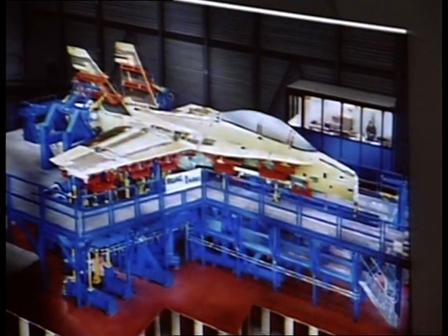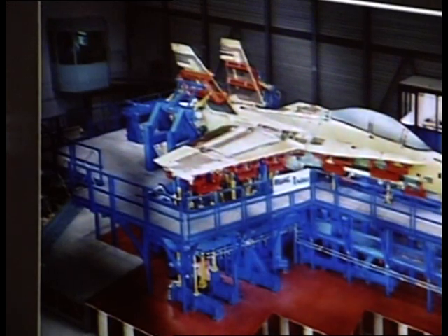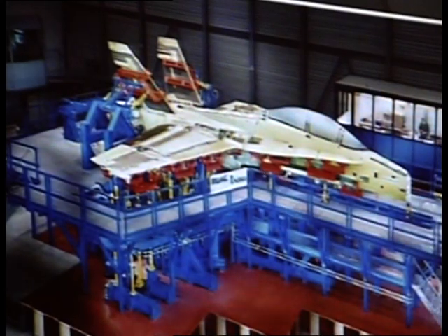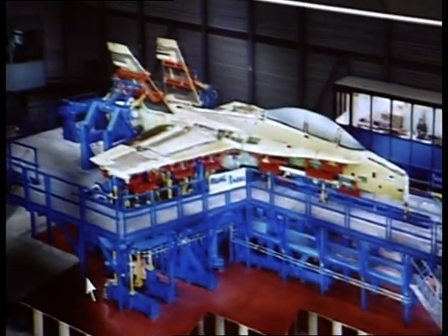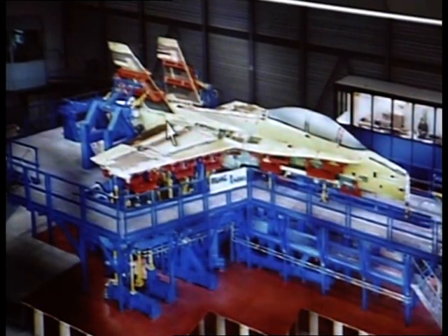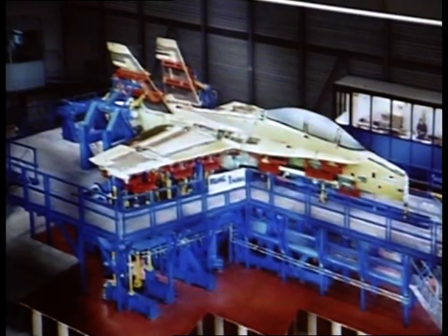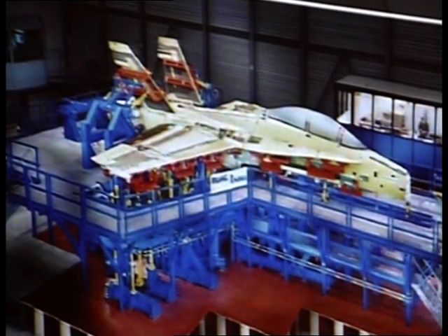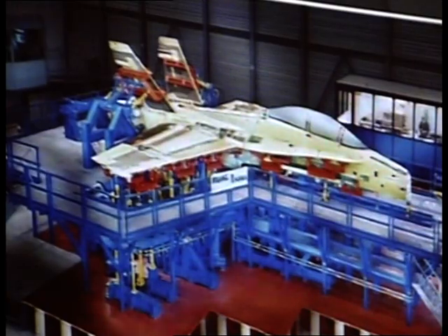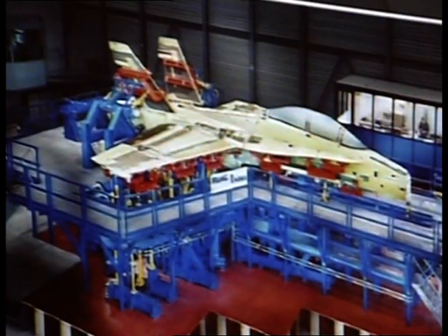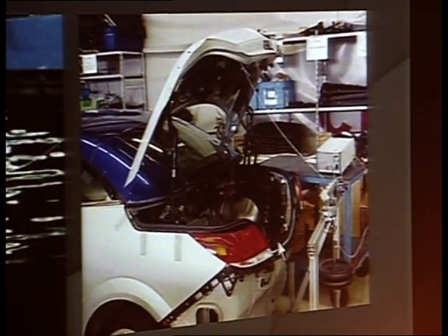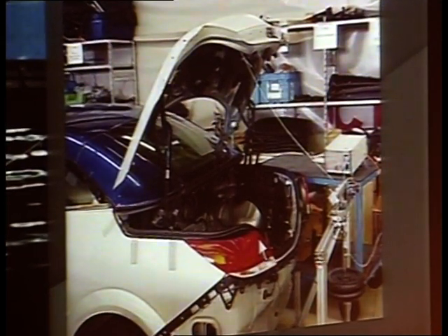Within 1 week, they needed to check whether it was the stiffness of the actual plane which is bad or the parameters inside the FE model. So we did these measurements using 4 of these trackers, putting them in the air, putting the whole plane full with LEDs. And we did the measurement job in 1 week, getting all the deformations out. Another application is motion measurements on parts. A simple example here: automotive industry, closures like cabrio roofs, doors, trunks. They want to evaluate, if you close them, how much overshoot there is.